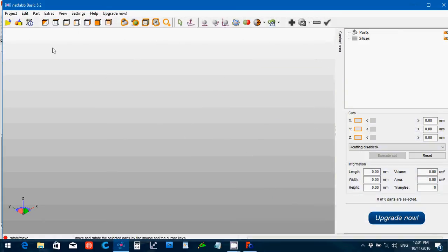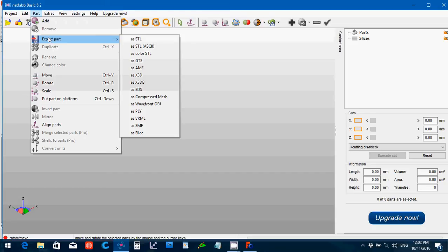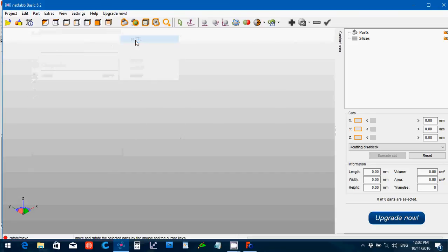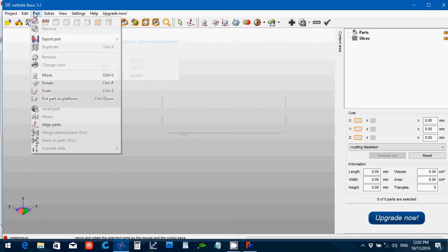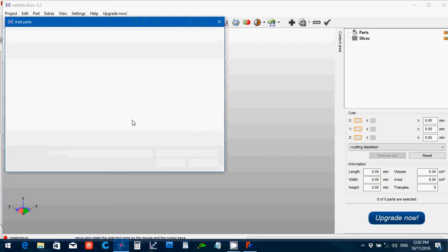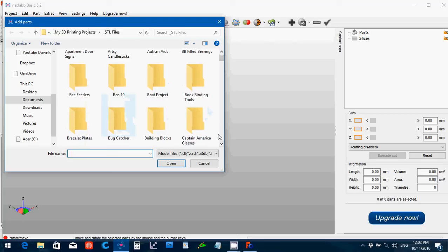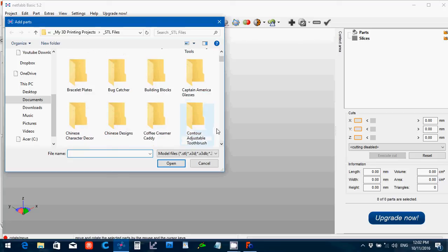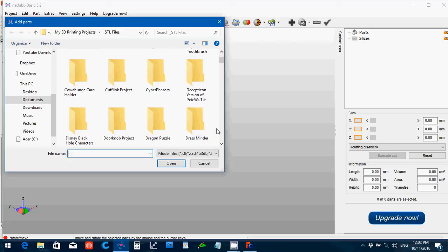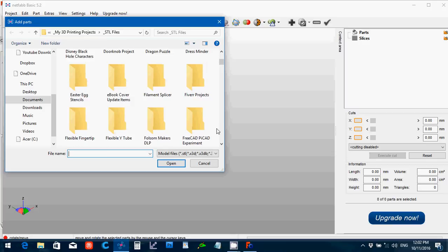Sometimes 3D printing is not cheaper than something that's mass manufactured. It's great for prototyping work, to get down what you're trying to do, but when it comes to actually mass producing something, the good old classic of getting it molded or CNC'd is probably cheaper than trying to do it through 3D printing.